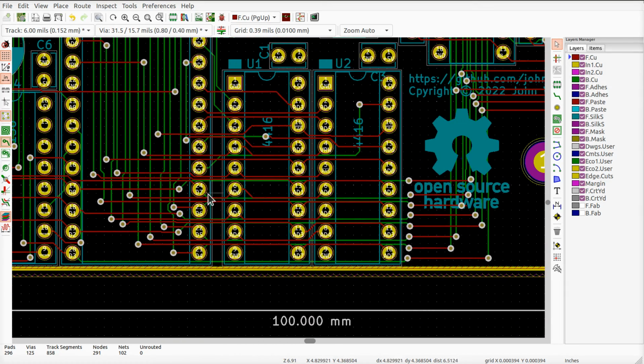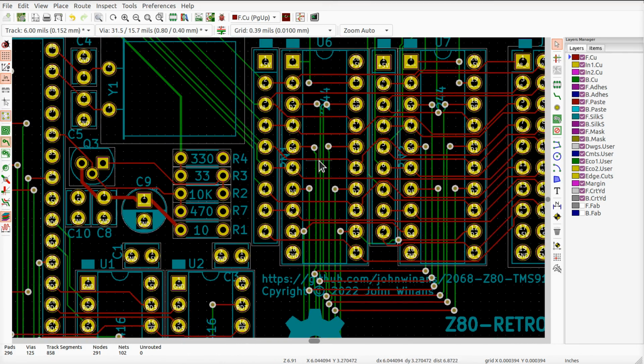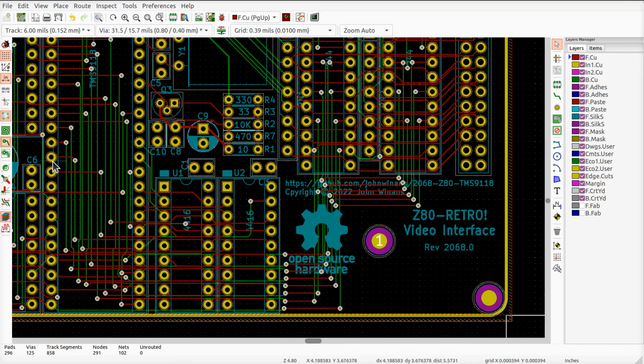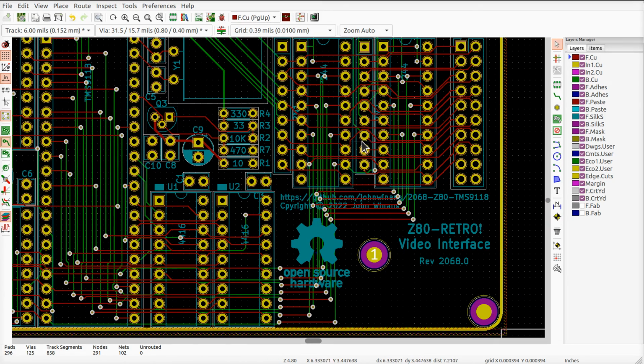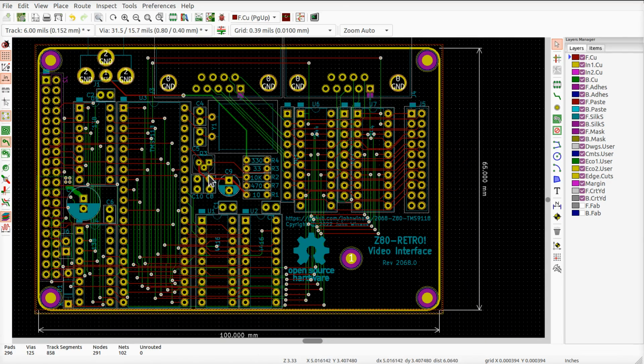And then these red lines run underneath the RAM over to here, up there, and then connect up to the 2 buffers here, the tri-state buffers that we use to take a peek at the joystick inputs over here. Okay, so the data lines on here, from the retro board, are coming over around and up and around here. That's kind of 4 inches, 5 inches of tracks here, and on the retro board they also kind of wind around a lot. Not really happy with all that.